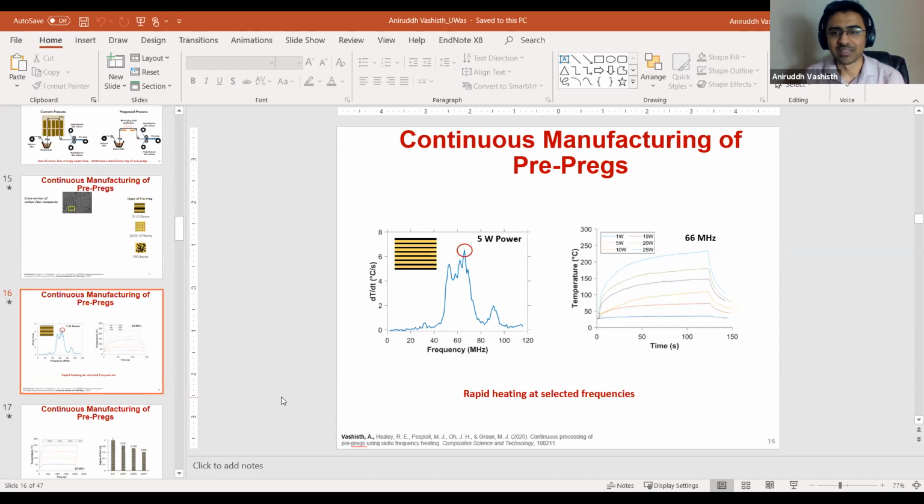And again, with temperature, interesting things happen. For example, for the simulations, we actually had the heat capacity and the conductivity of the material as a function of temperature. So that actually played a really important role in basically tracing the experimental temperature time curves as well.